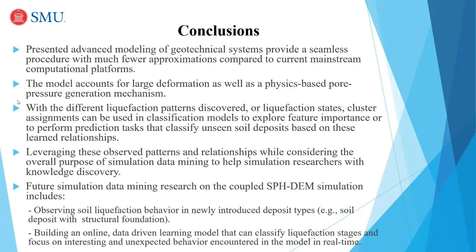This is not common if you do finite element modeling or finite difference modeling. If you use Plaxis or you use FLAC, you know that every time you need to tweak a few things. Oh, it needs to be a little bit modified, a little bit fine-tuned. Here, not, because we're trying to go as fundamental as possible, trying to base our modeling on first principles, with less room for empirical assumptions.